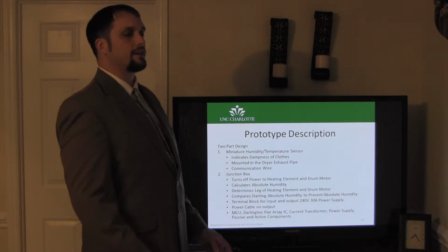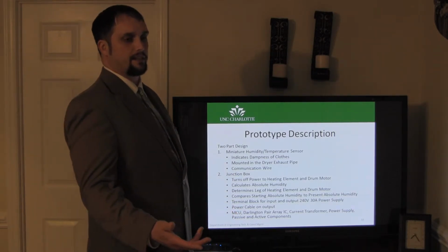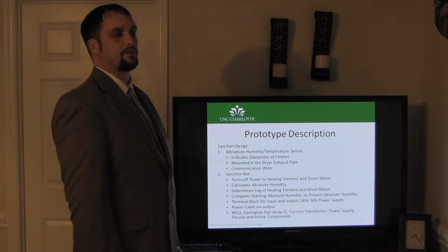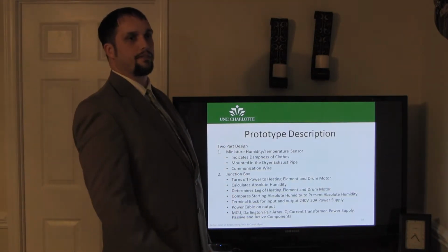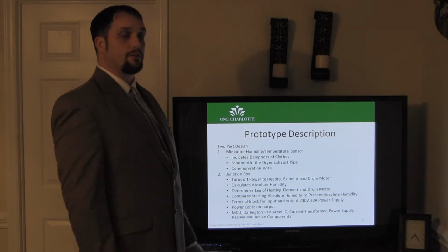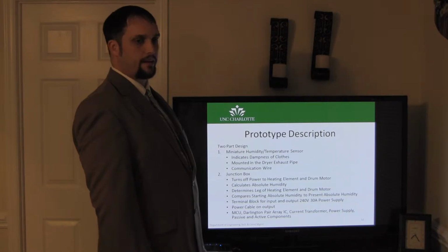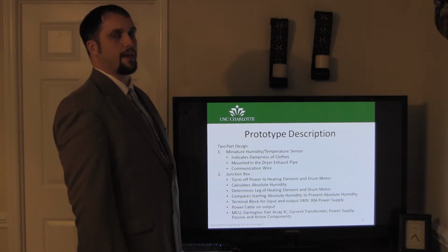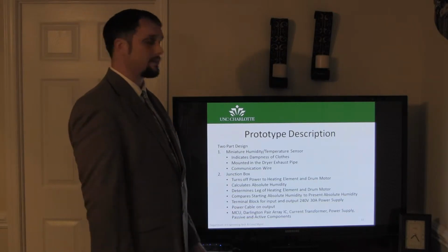So you can tell which one is which. Like the case I just gave you, if the current drops to 500 milliamps, then you know that leg is your heating element. If it never goes below 2 amps, then you know that is your drum leg. So you can determine that by a current transformer and just monitoring the currents throughout the drying cycle.